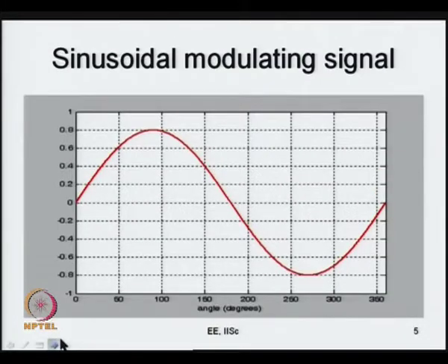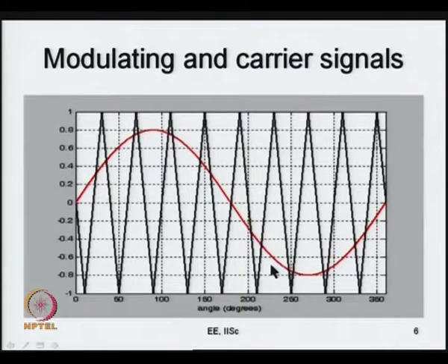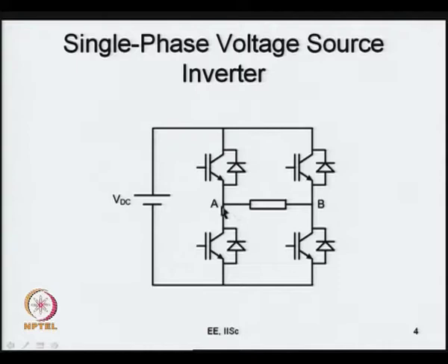If you go to that unipolar PWM, first let us just look at one leg and one sine wave corresponding to a leg. So, why do we use a sine wave? The idea is that the voltage at this pole, we want it to be modulated in a sinusoidal fashion with respect to the DC bus midpoint. That DC bus midpoint is not indicated here. You can regard this VDC as VDC by 2 and another VDC by 2, and the midpoint can be regarded as O. So, that is the DC bus neutral.